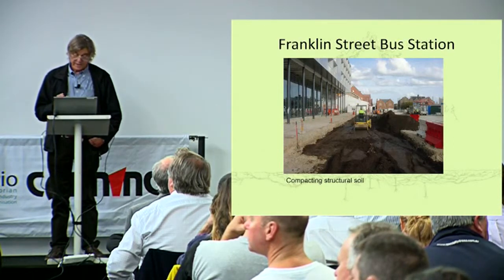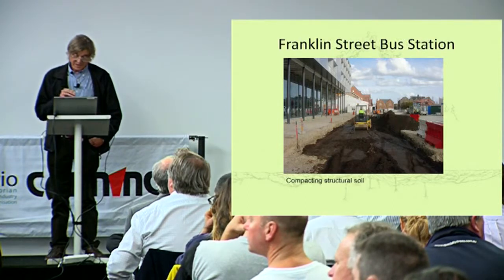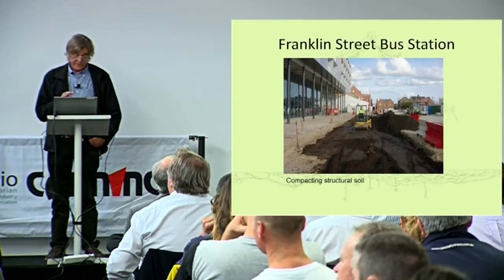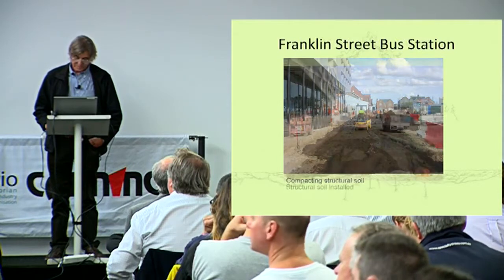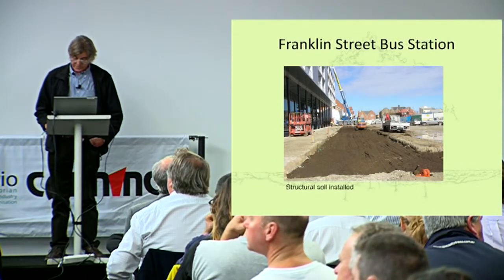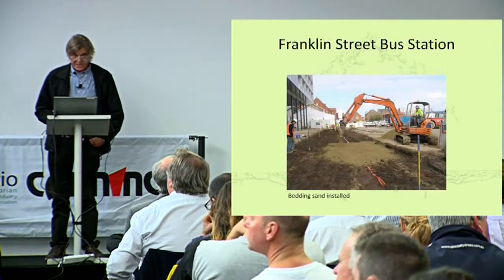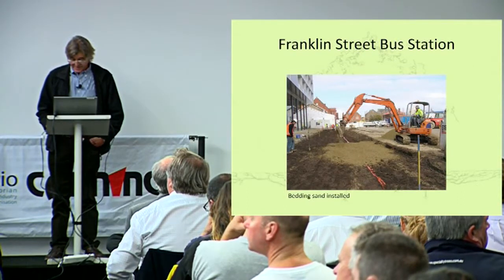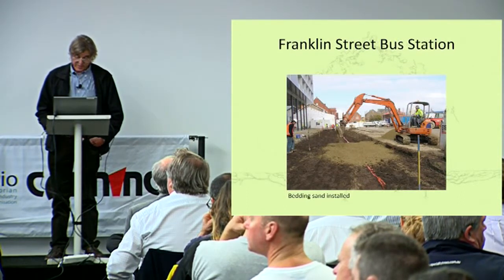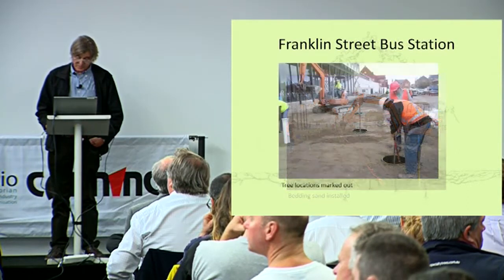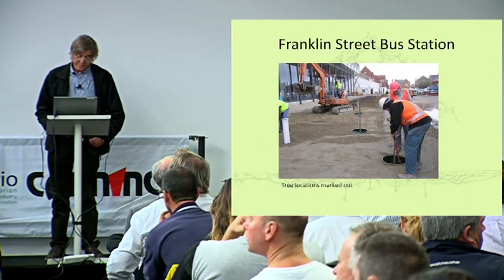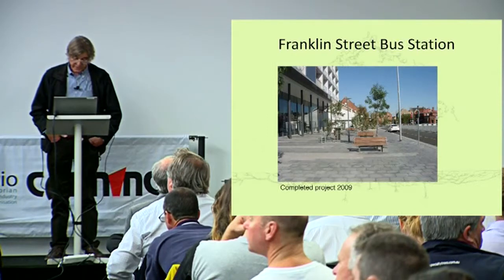The soils were allowed to get wet, so compaction wasn't ideal in this situation, but it hasn't actually affected the structural strength of the soil. So the structural soil was installed, bedding sand was installed over the structural soil, tree pits were marked out, and that was a completed project about 5 years ago.